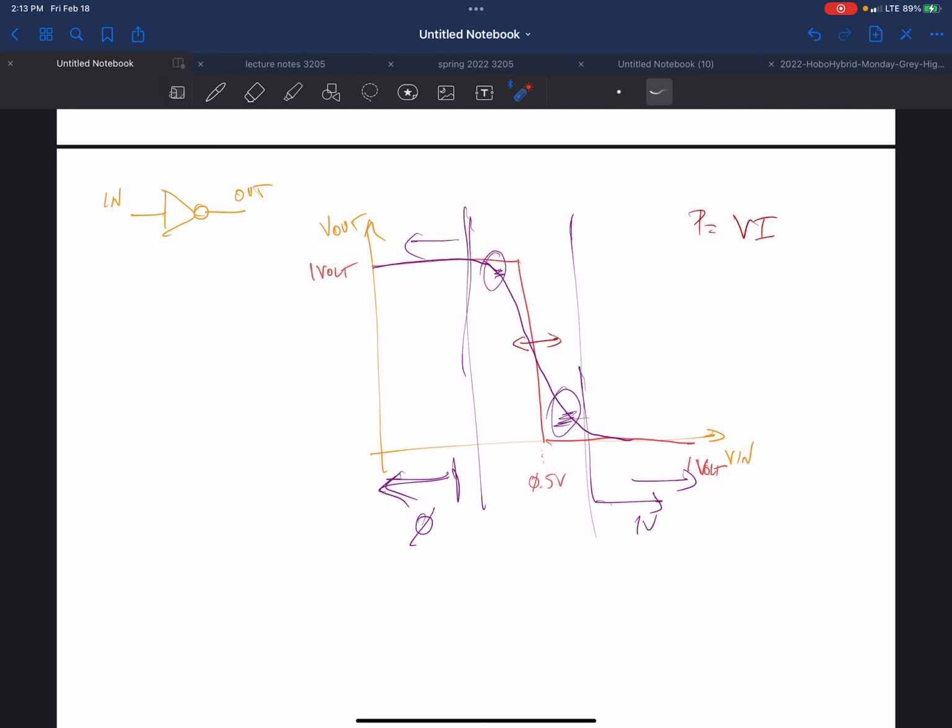Can you repeat the first reason? Yeah, it's that you can use your full power supply. So if you have a 1 volt power supply, your binary 1 can be 1 volt, and your binary 0 can be 0 volts. You don't have anything to compare to, so you have to take my word for it, but alternative logic families did not have that.